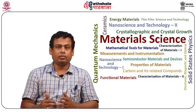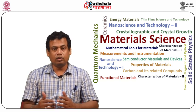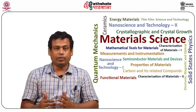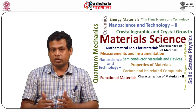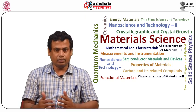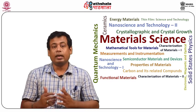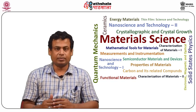Simple solvents include acetone, methyl ethyl ketone and methyl isobutyl ketone, which are chemicals used for resist stripping and lift-off processes. Additional oxygen plasma cleaning is effective for removing residual resist or any organic contaminations during the lithography process.